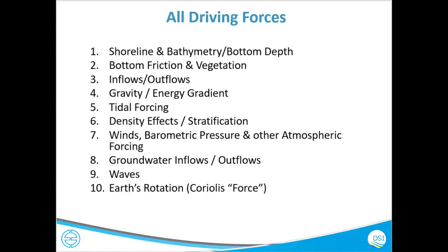So the driving forces in any water body could be one of these. I might be missing something. If you can find out, let me know, I'll add it. So the important things you need are shoreline and bathymetry. You always need to cover your shoreline as accurately as possible. If you have a really meandering and braided river, consider bottom friction and vegetation. If you have a study area with a lot of vegetation, you want to consider it because it resists the flow, and it would have an impact on water quality because there will be respiration and photosynthesis.